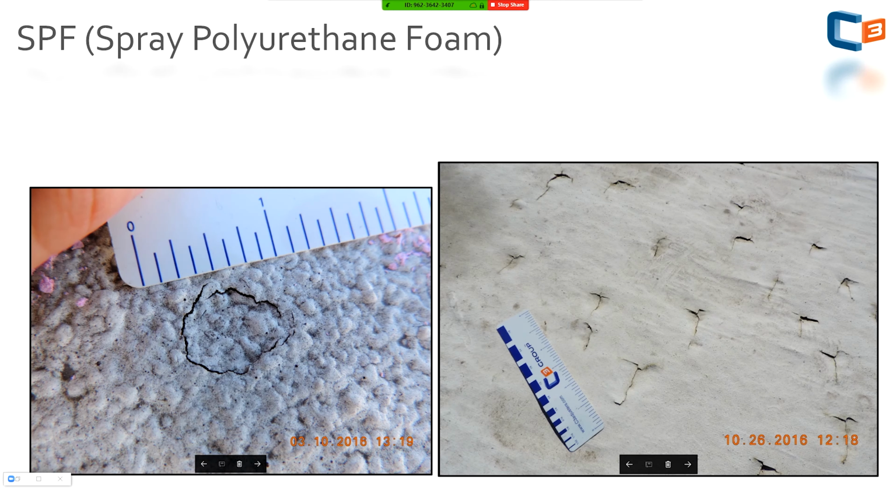So when we're looking at these, this is a foam product. It's spray foam. You know what hail is going to do to this. It's very compressible. So if you have a hail impact, it's going to fracture that. On the left-hand side, we have an elastomeric top coat. Similar to other roof systems, we have a UV protectant. That can be an elastomeric top coat, or it can be granules embedded in a glue or adhesive they set when they cure the SPF. But in this case, we had elastomeric, and you can see the fracturing.